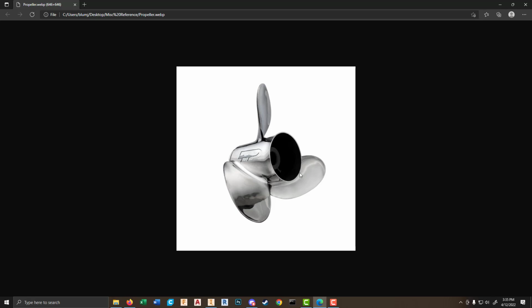But then how on earth are we going to make these blades, right? They are a very funky shape. And as I look at them, I sort of see here, as I trace along this line, that this is a bit like a spiral going up, right? And we've got sort of a smaller spiral on the inside and a bigger spiral on the outside. And then we've cut out the shape from that, right? If you can imagine taking a sheet of metal and twisting it, and then cutting out the shape from that twisted piece of metal. And that is exactly what we are going to do in Inventor.